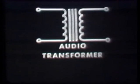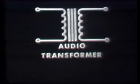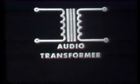Like the power transformer, the audio transformer, too, is usually constructed with an iron core. At frequencies above 20,000 cycles per second, the RF transformer comes into use. At these frequencies, hysteresis and eddy current losses in an iron core become so great they have to be prevented. Therefore, RF transformers generally have an air core.